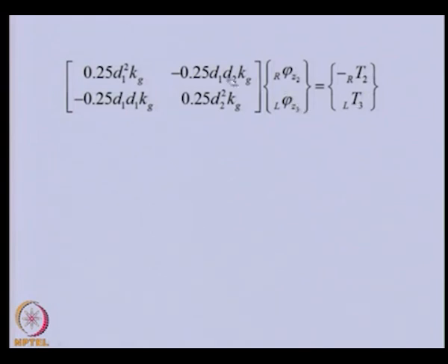Once we have the elemental equation for that spring element, we can develop the elemental equation for the whole system. That means we have developed it for this, the spring, and this. So elements 1, 2, 3 can be combined, and then we can apply the boundary conditions. The main focus of this illustration is that this is the elemental equation for the spring which is there between the two gears because of its flexibility.